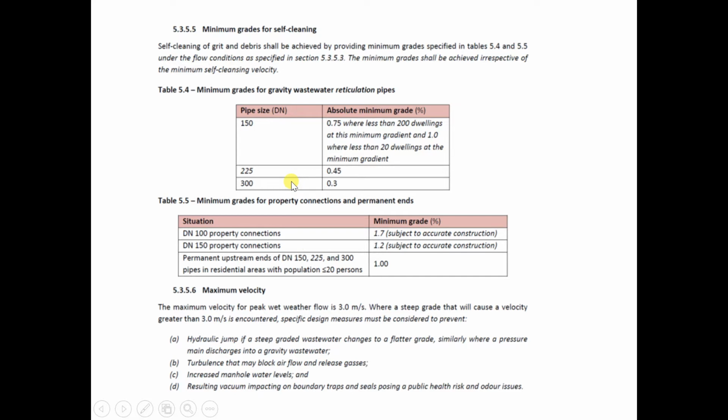And these are the sewer pipes. The slope needs to be greater than the stormwater pipes. So we'll be looking at the nominal diameter 150, and a slope of 1.2%.